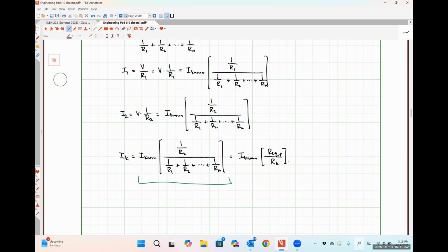So this particular formulation of current division works for literally any number of resistive paths that are connected in parallel. Okay. A lot of textbooks only derive this out for exactly 2 resistors in parallel, and I'm going to show you what that looks like, just because in some of my old test solutions, I used that old method, and so I want you to know where it's coming from, okay? But as of the last 3 or 4 years, really, I only teach current division this way, and I only apply it this way using the reciprocals of the resistors.